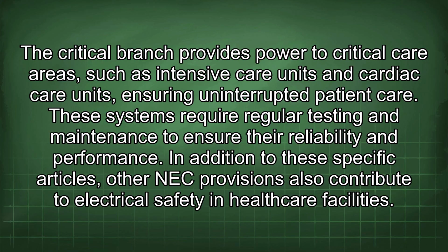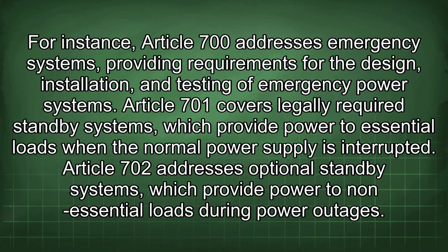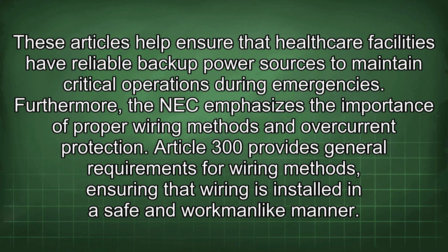In addition to these specific articles, other NEC provisions also contribute to electrical safety in healthcare facilities. For instance, Article 700 addresses emergency systems, providing requirements for the design, installation, and testing of emergency power systems. Article 701 covers legally required standby systems, which provide power to essential loads when the normal power supply is interrupted. Article 702 addresses optional standby systems, which provide power to non-essential loads during power outages. These articles help ensure that healthcare facilities have reliable backup power sources to maintain critical operations during emergencies.